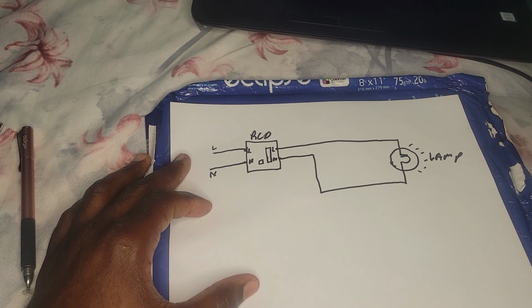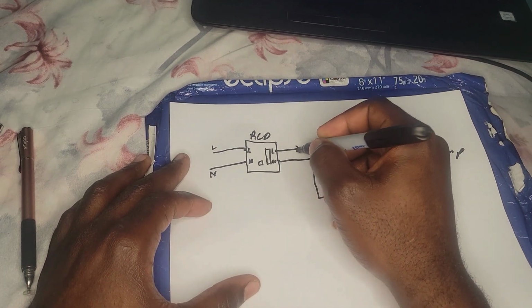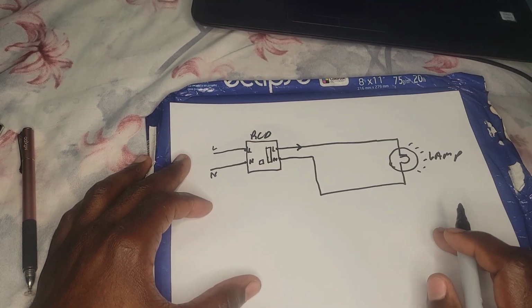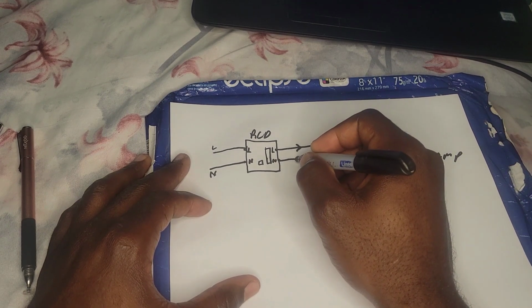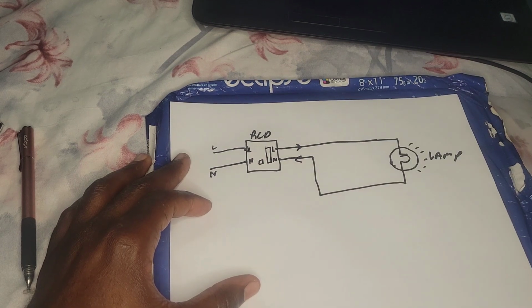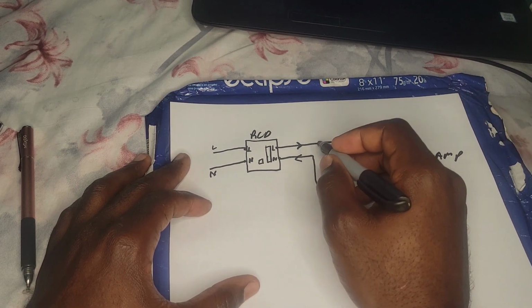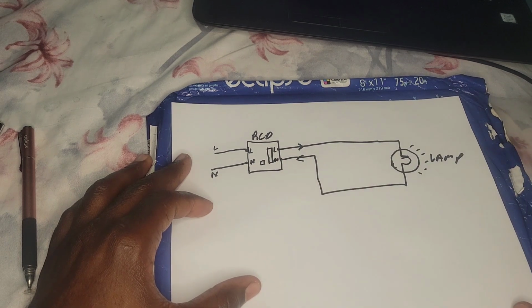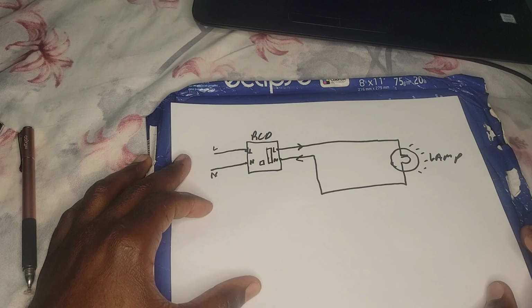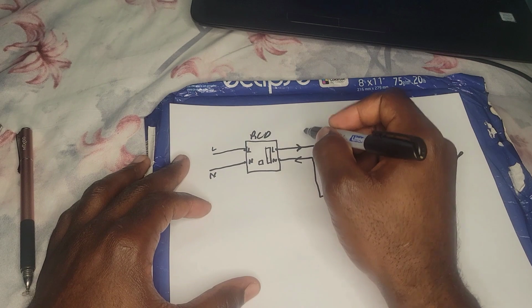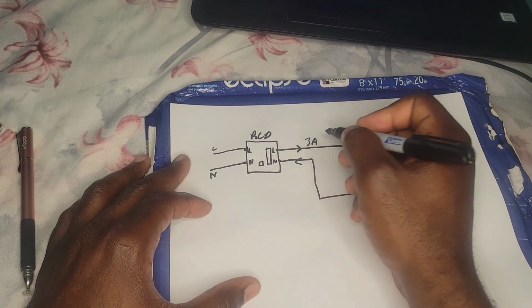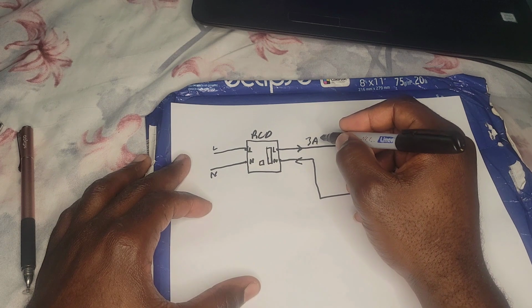How that summation current transformer works is that it constantly measures the current going out in the live, which is the source, and the current returning in the neutral. So the source going out and the return that comes in the neutral. The sum of this is supposed to give you 0. In normal condition, let's say we have 3 amp, just throwing out some random numbers here.